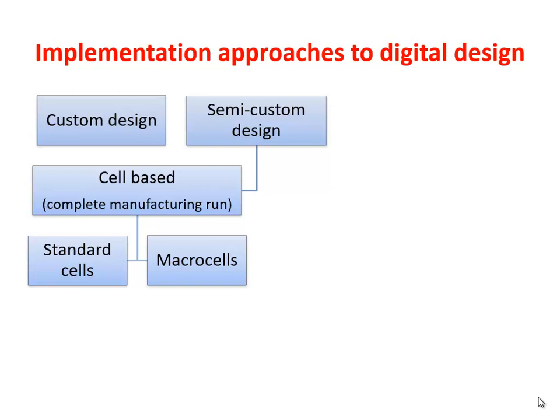The large block can be a memory array, but in some cases can be a complete small microprocessor to put on the whole chip. For example, in some FPGA chips, there are small processors available that are put on the chip design as a single macro cell.